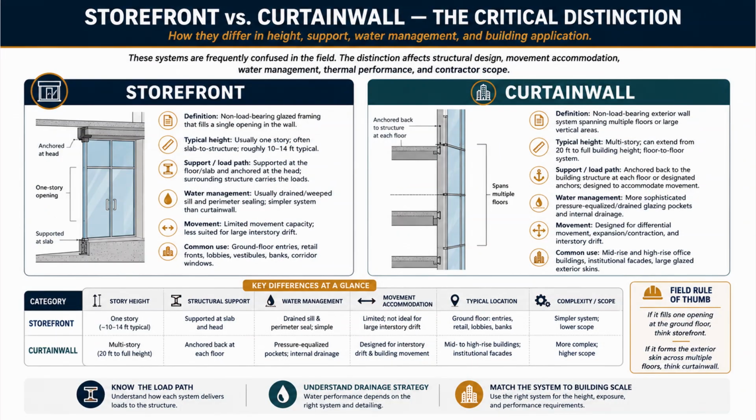This is the most important slide of the day, the way door handing was the key slide last class. Storefront versus Curtainwall. These two systems are frequently confused in the field, and the subtitle tells you why it matters. The distinction affects structural design, movement accommodation, water management, thermal performance, and contractor scope.